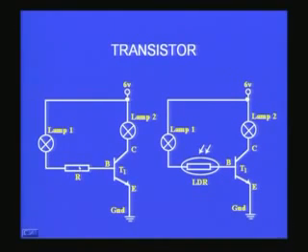But this is only the base current. This base current will produce a large collector current in this circuit, and therefore you would find the lamp in the collector will be very bright. There will be a large current flowing from the 6 volts through the collector and the emitter, and therefore the lamp will glow brightly, but this current will flow only as long as there is current provided by the base circuit.